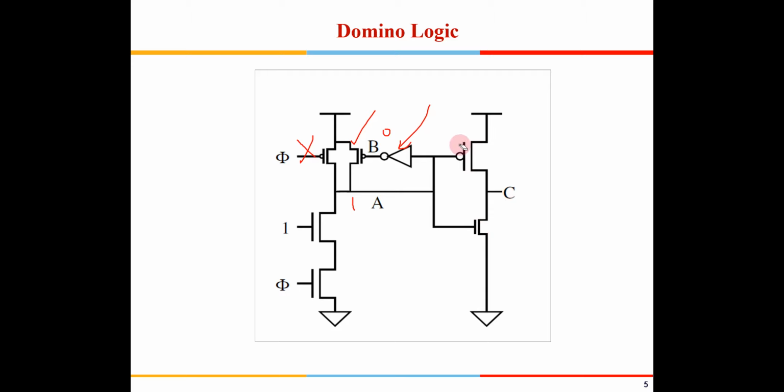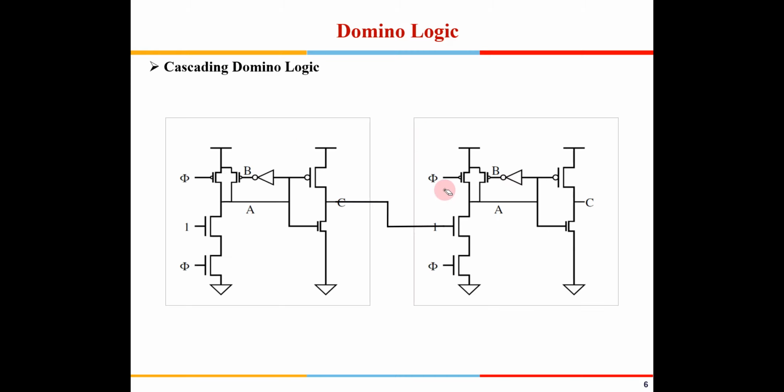So this is what the domino logic is. Now what is the advantage of having this inverter? We'll see that. If I have an inverter out here, now the cascading is not a problem, right? So one inverter I have placed here, which will resolve my charge sharing problem, and this inverter which is placed here will not cause any cascading issues.